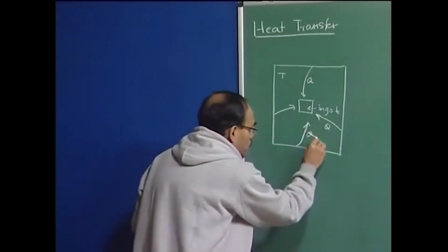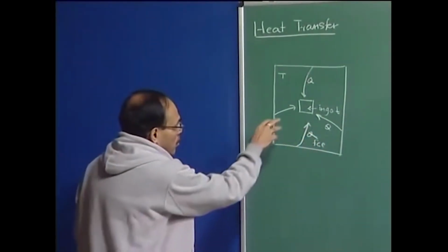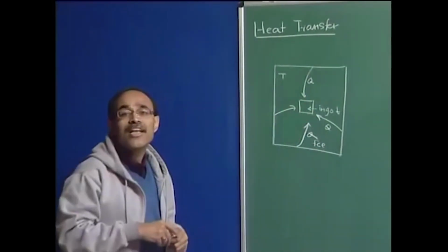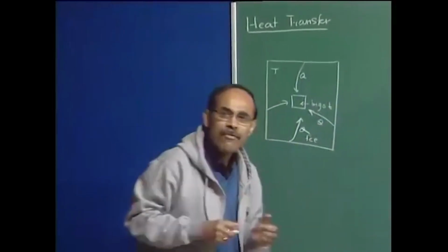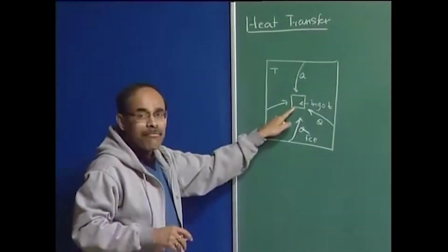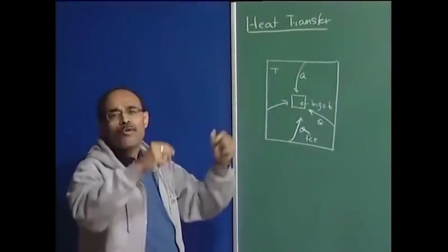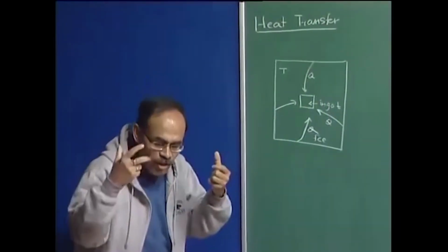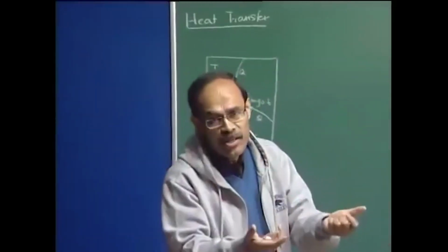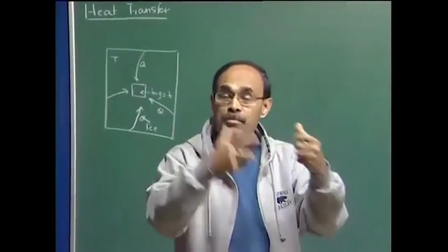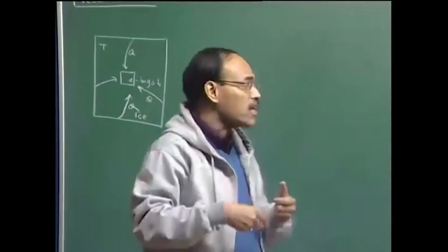Now, if you want to predict the homogenization time, suppose I have an ingot and I place it within the furnace, and I want to find out at what time the ingot has become completely homogeneous, and only then I am going to take out the ingot from the furnace and subject it to either soaking pits, where the same temperature is maintained, or straightforward taking it to the rolling mill.